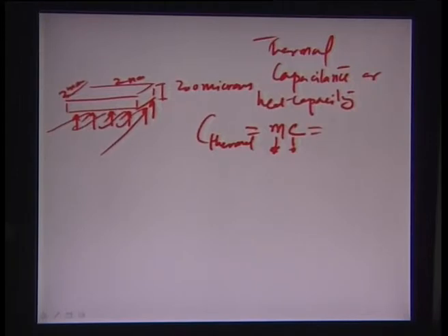So essentially it is again rho times the area of cross section, which is A square, times the depth. In this case the depth, from the heating side to the open or the atmospheric side, is D. So we assume this to be A and this to be D. So rho A square D is the total mass, and then of course you have the specific heat C.